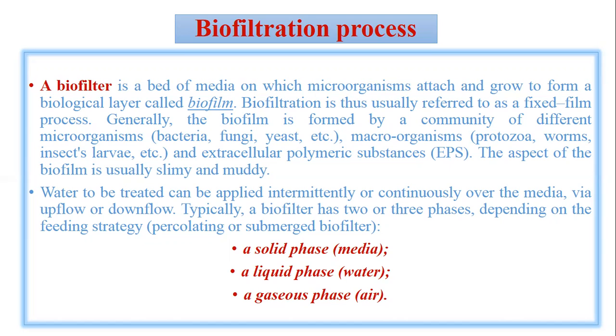Water to be treated can be applied intermittently or continuously over the media via upflow or downflow. Typically, a biofilter has 2 or 3 phases depending on the feeding strategy. Percolating or submerged biofilter: a solid phase media, a liquid phase water, a gaseous phase air.